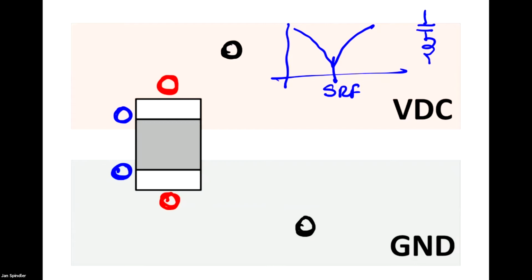This is not the inductance that is important. This is part of the inductance that is important. But the important thing is how is the loop where this capacitor is introduced. If the loop is small, the total inductance, not the partial inductance, will be minimum. And with a minimum inductance, you will have less problems, no?